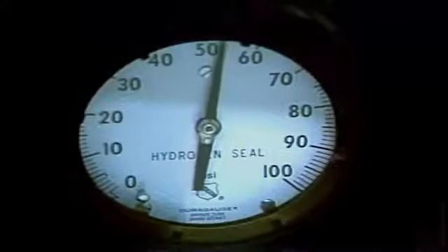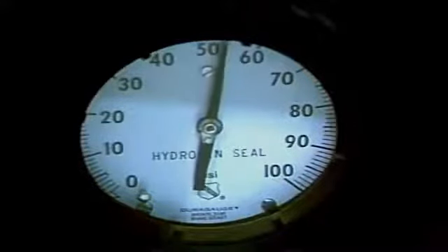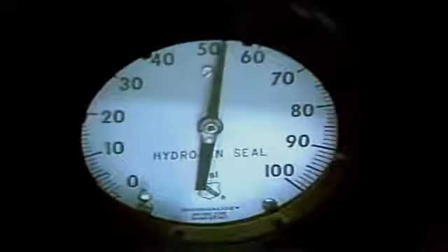This maneuver takes several hours to complete, so it is clearly necessary to get an early start and plan the complete operation when returning a unit to service. During a short shutdown, say overnight or even for a few days, it is normal to leave the generator rotating on the turning gear and to keep the generator charged with hydrogen. Of course, if the generator is air-cooled, then we would not be faced with hydrogen charging. However, there is another more vital reason for keeping the unit turning over when it is taken off load.